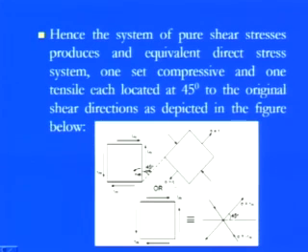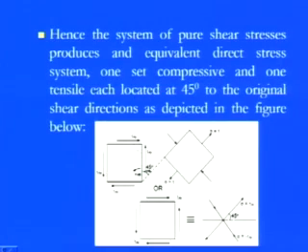So what we have is that only at the 45 degree angle are these stresses completely converted into normal stresses. The shear stresses and counter shear stresses are applied there, but at the end, simply by rotating this element, all the shear stresses are exactly converted to the normal stresses.